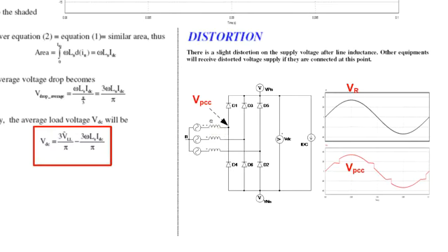From that point of common coupling, you have load 1 as your rectifier, and load 2 can be other loads, such as your PC or laptop. Because of the rectifier and the source inductance operation, we see that the VPCC, the voltage at the point of common coupling, is being distorted.